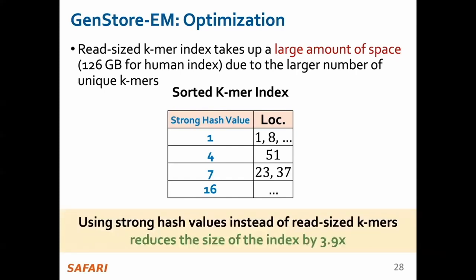And this index is still larger than the baseline k-mer index used in the conventional read mappers. However, our proposal is feasible for in-storage processing because of the large capacity and high internal bandwidth of modern NAND flash-based SSDs. Basically, we trade off the storage space and the number of elements in the table so that we fit within the constraints of the architecture that we're designing this accelerator for. It is very critical to avoid random accesses, and sequential accesses are much more efficient. So we trade off to increase the size of the data structure based on these constraints.